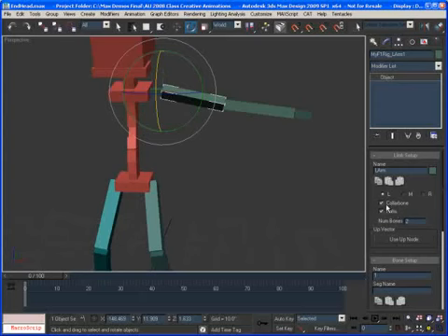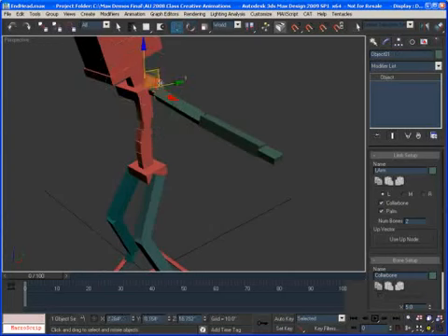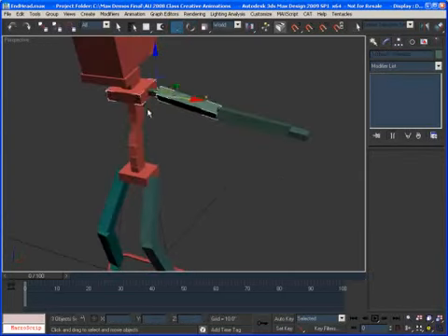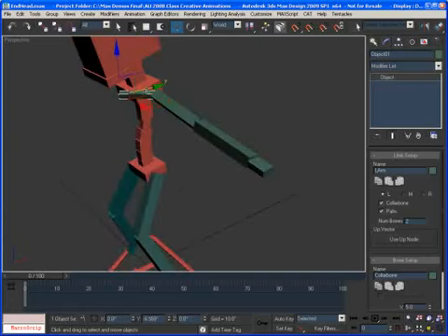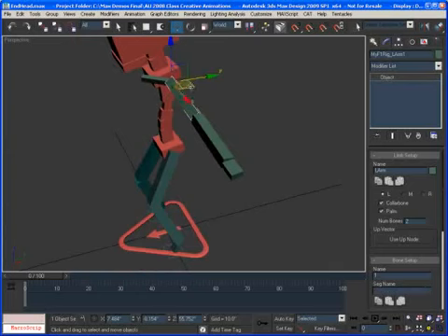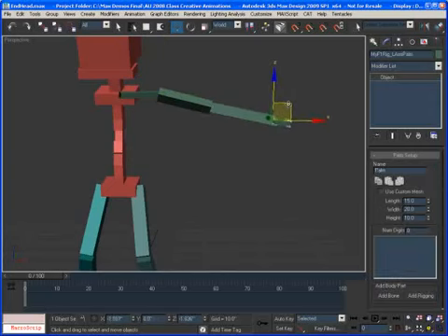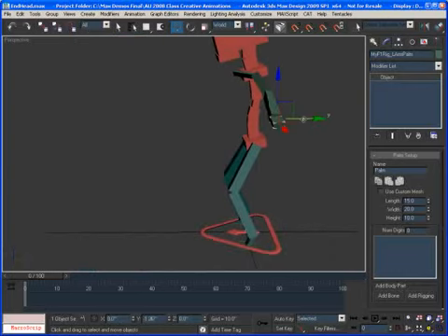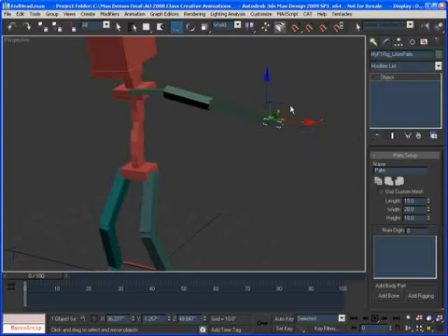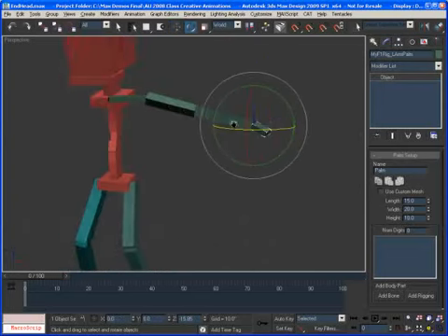So if you take a look here, it's still called a collarbone. If I turn that off, it removes the clavicle. If I turn that back on, you see that the clavicle is there. So now I can grab this clavicle and bring it a bit forward like that, like a regular human being, and just bring the shoulder like that, and define this is where I want that to be started. So now we've got the clavicle, we've got the IK chain that starts here. So if I grab the end like that and move it like so, we're still in setup mode, rotate it a bit like so, and now we've got our setup for the arm.